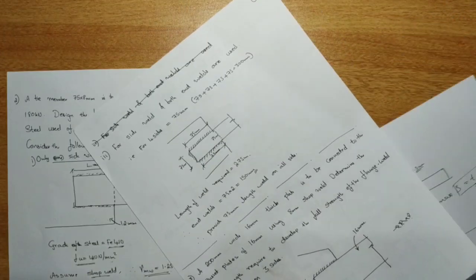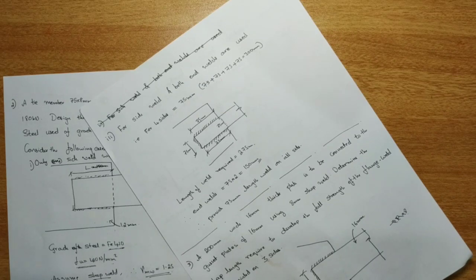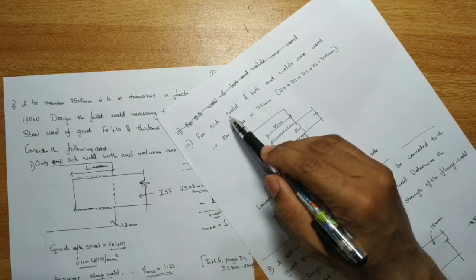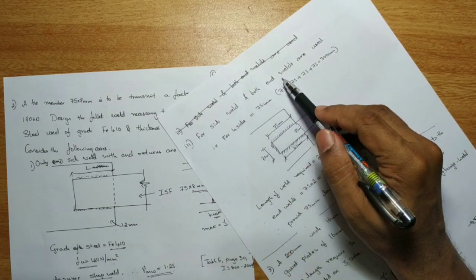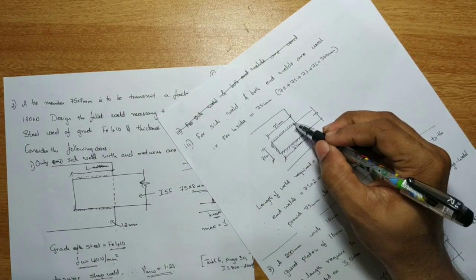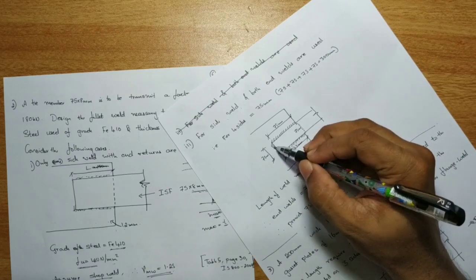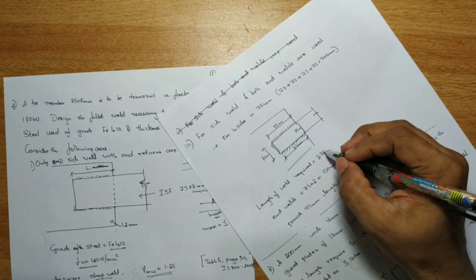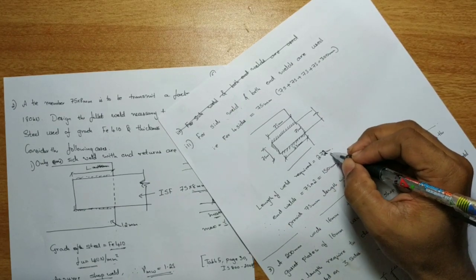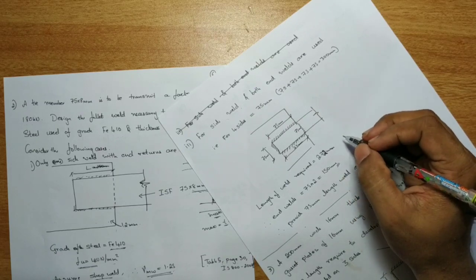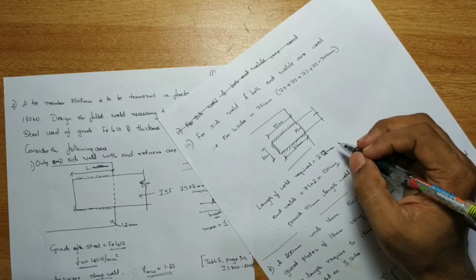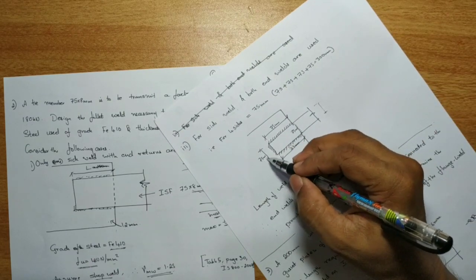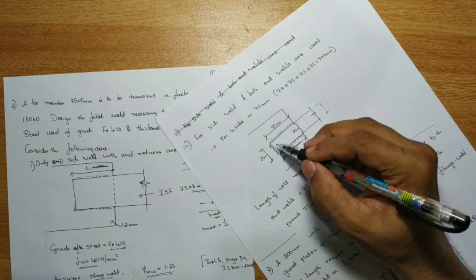And next, the third case, here they have given side weld. You need to provide side weld and both end welds you need to provide. Anyhow, you know this is a side weld, and both end welds you need to provide. The length required was 272 mm, right? The calculation will be the same up to LW. LW was 272. Anyhow, this part is 75 and this width is 75.